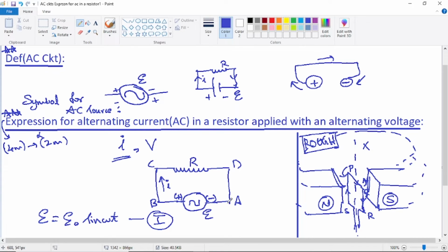The voltage law simply states that the algebraic sum of all the changes in potential, which is also called potential difference, in a complete traversal of a closed circuit will be 0. That means as we move from point A, going around the circuit and coming back to A, on the way we'll go through different changes in potential. For example, when we go through a resistor, there is a potential difference across the resistor. This potential difference across the resistor is denoted by the symbol V. I'll move the I and V symbols away from the circuit diagram so they won't disturb the derivation.